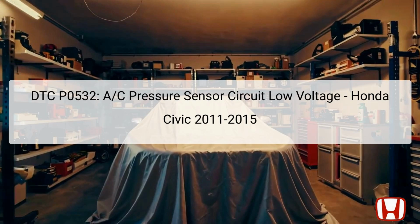The sensor is located within the AC pressure sensor 3P connector in the engine compartment, typically near the AC evaporator box. A low voltage reading from this sensor can result in inadequate AC performance and various discrepancies in the overall HVAC system function. Comprehensive troubleshooting is required to identify the root cause of this code, which may include wiring issues, potential sensor faults, or ECM malfunctions. Follow the prescribed troubleshooting steps systematically to ensure accurate diagnosis and resolution.